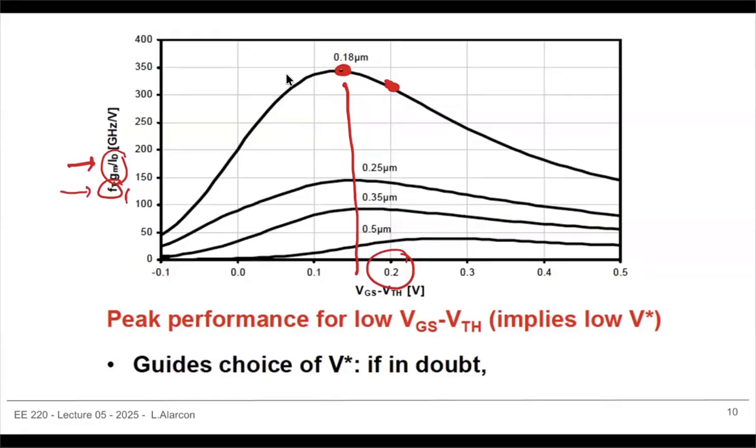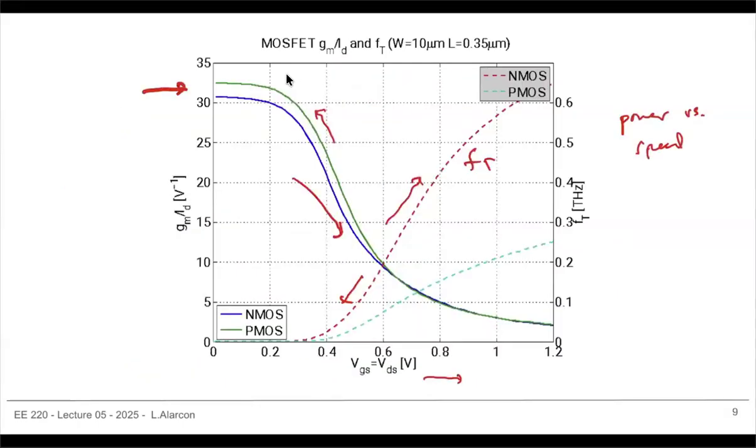And having said that, if I want more power efficiency, I can change my bias and move this way, to the left, for a bit. Or if I see that I might need more bandwidth, my bandwidth is too small, the performance at speed is actually slow, then I can move the bias point a bit closer to the right and get a higher FT per transistor.